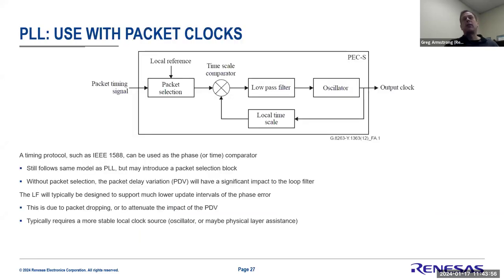Now you might ask, well, why am I talking about PLLs? Because I'm showing physical clocks coming in and physical clocks coming out. But that's not to say that PLLs can't be used for packet-based clocks as well. And it's very commonly used for packet-based clocks, especially when you look at doing phase and time clock distribution over networks and using it for applications like telecom, where you need to resynthesize clocks like RF clocks for radio units.